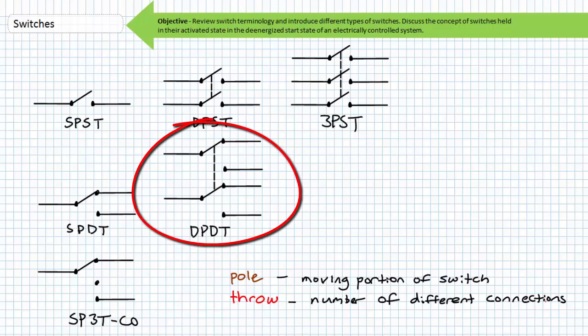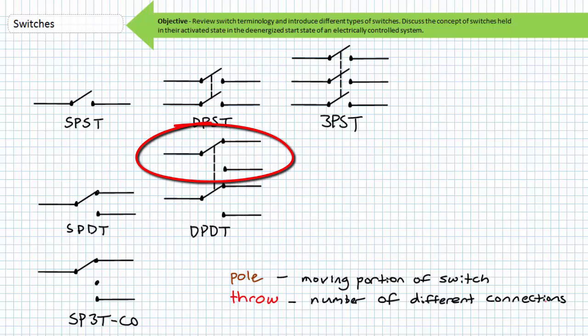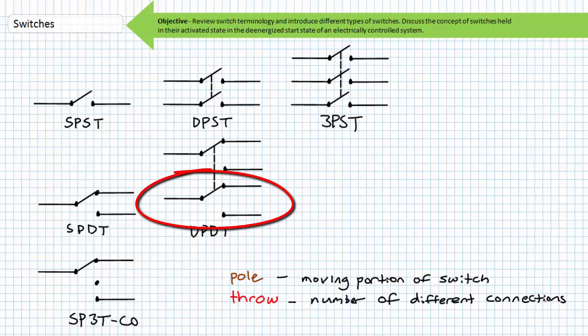Consider a double pole double throw switch, DPDT. This is just like two ganged single pole double throw switches mechanically linked with a single action. The top single pole double throw switch is electrically isolated from the bottom switch. However, the terminal on the left is now the common servicing both terminals on the right for the associated switch. The mechanical linkage's only purpose is to transfer contacts simultaneously.